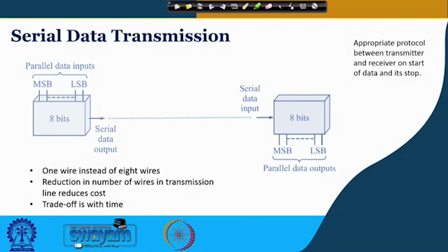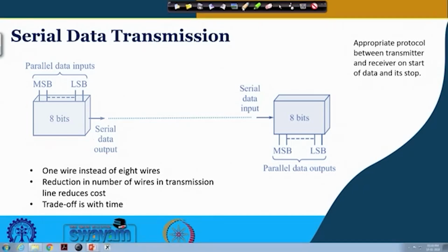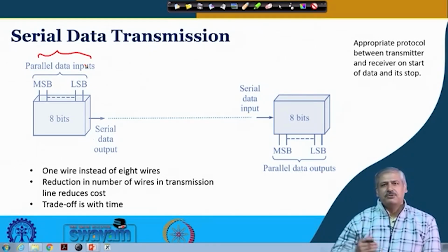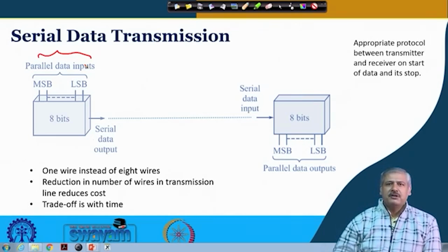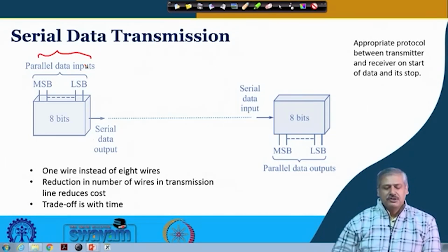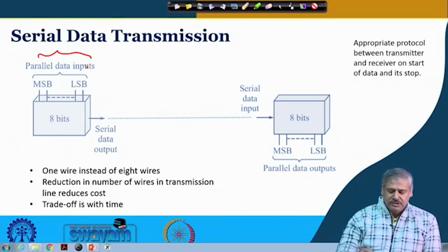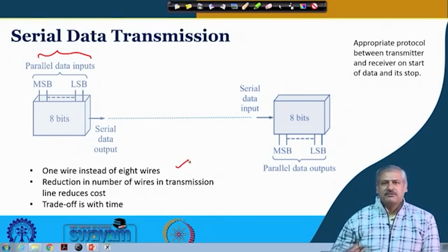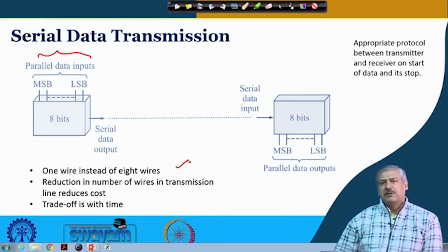that we do through a shift register. It can be used for converting a parallel stream of data that is getting generated. For example, in some process say 8-bit data is generated, samples are generated which are encoded by 8 bits. So, one sample means 8 bits are getting generated and it needs to be transmitted to some other place. One option is to have 8 transmission channels, so that at the other side those 8 bits will be appropriately collected, but having those 8 wires or 8 channels is a bit costly.